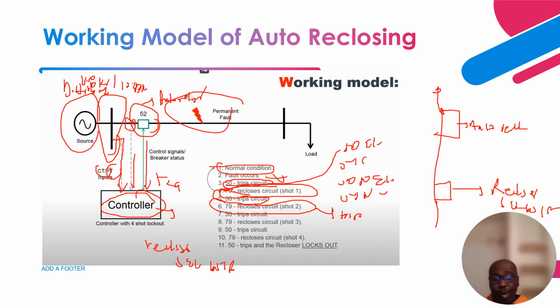Depending on the customer, let's say you have a foundry or a fabrication facility that deals with semiconductors, they do not like those temporary dips in power. So they will rather allow the fuses that are downstream to take care of the fault instead of the auto reclosing, opening and closing.